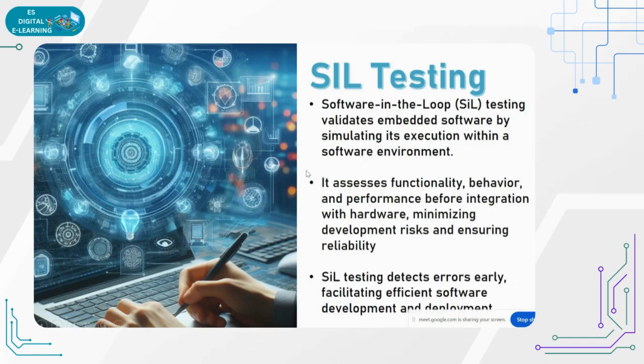So SIL testing is specifically the same function, where we are checking the functionality, behavior and performance of the complete system. Because whatever we are doing in the modeling, there also we are checking the functionality, behavior and performance. So in SIL testing also, we need to do this. This is very important to detect early errors.